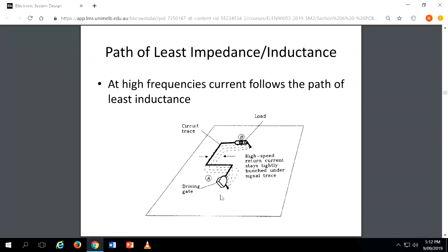That is the reason when you make a ground plane for high frequencies, you have to keep this in mind. Your return signal will be like this. Maybe you put a cut there, then it can't go. That is the reason auto routing might not be good. Auto routing for high frequencies might create issues. Even for your DSO, it might mess up your ground planes. Please don't use auto routing.